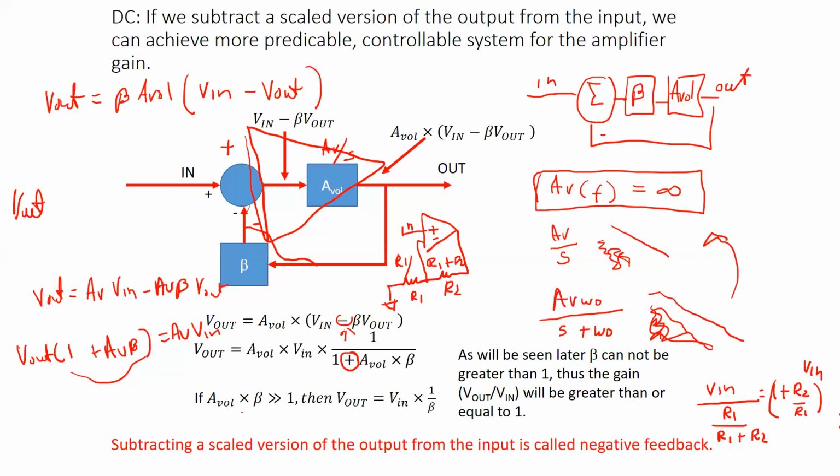Whereas before we might have used nodal analysis and this equation, V out equals AV times V plus minus V minus, now we're actually using a system methodology or a flow diagram, right? And we just take our beta as the voltage division. It's an ideal op amp, so no current is flowing in. So we're getting that voltage division there.